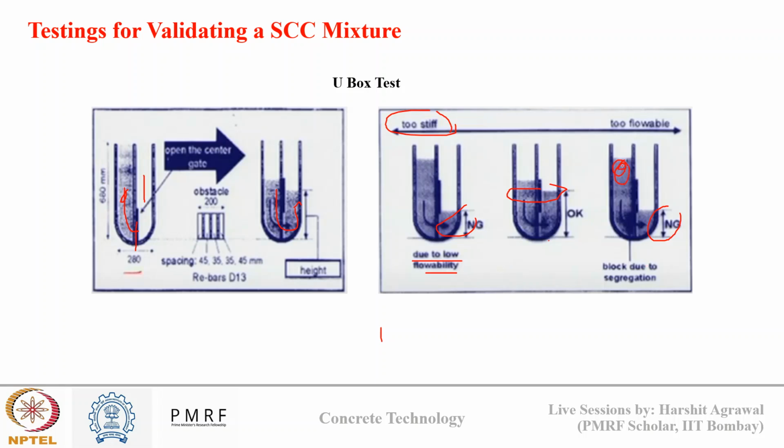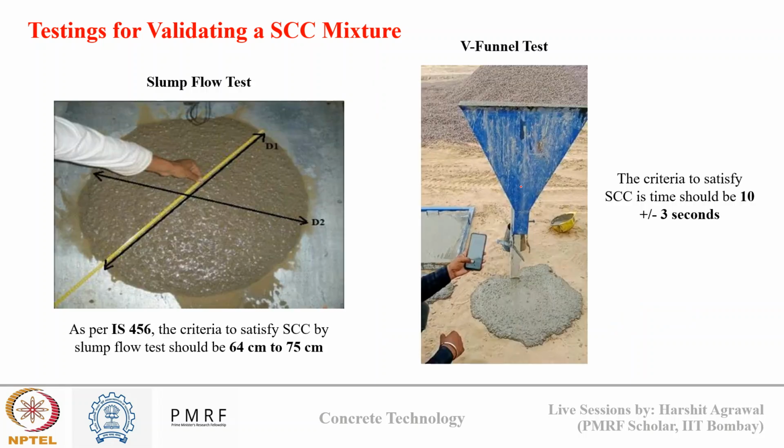You may see all the water coming up here and the cement paste here. That can show you whether we have added SP beyond a limit, which has led to bleeding, or if there is not enough viscosity modifying admixture to keep the concrete cohesive. So using this test we can make that judgment.